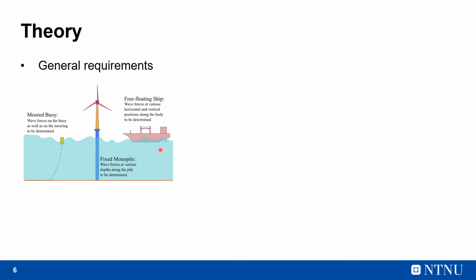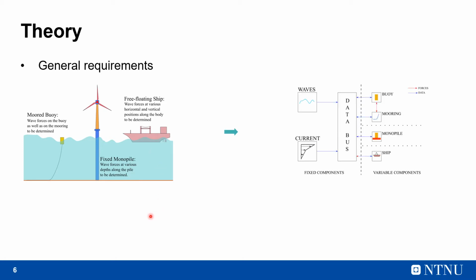This means that we are not much concerned about what goes on in regions away from the body surface. So one effective way of simulating this is to have component models for waves and currents that generate the parameters that define the waves and currents at a particular location, and supply these parameters to a database from which the object component models can then make use of these parameters and then use the spatial information contained within the object model to calculate the wave and current loads at that location.